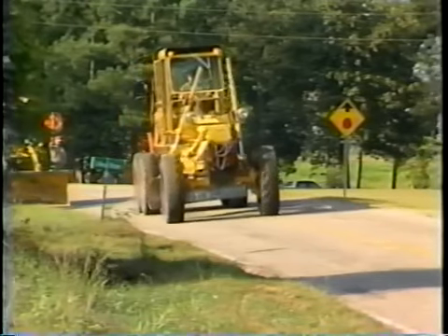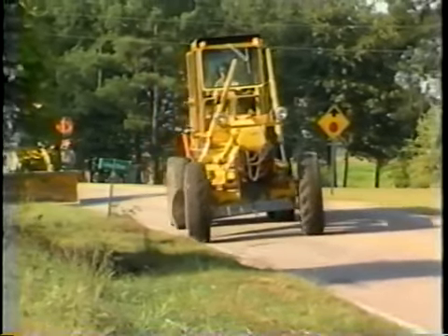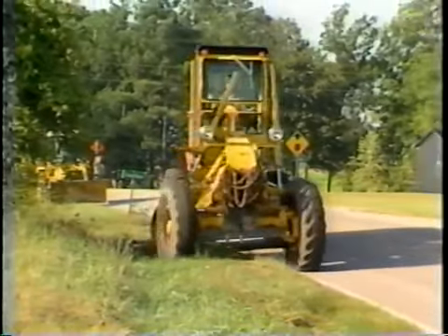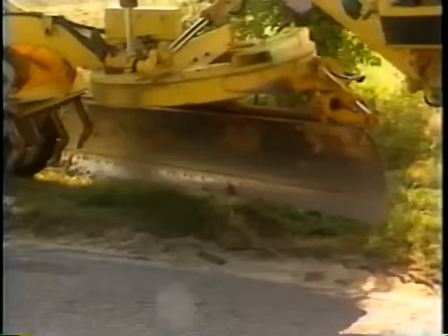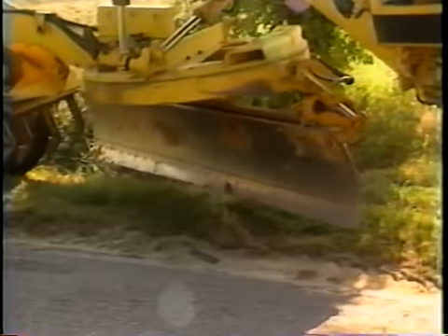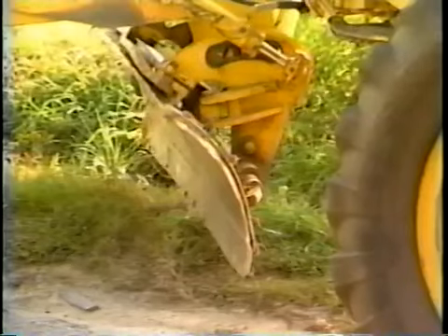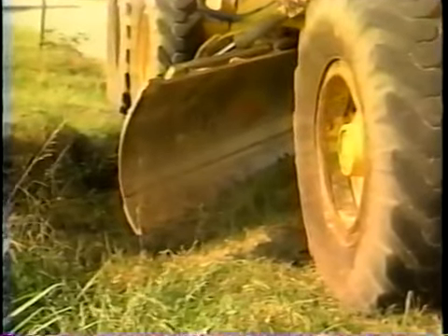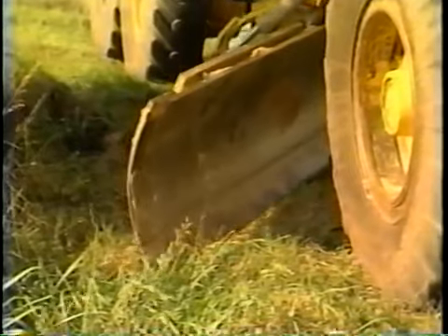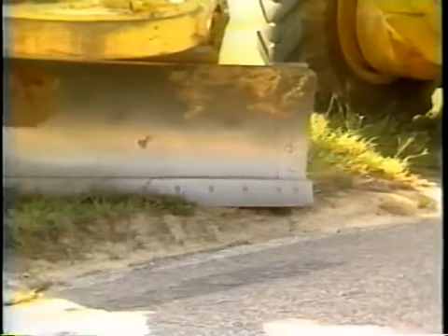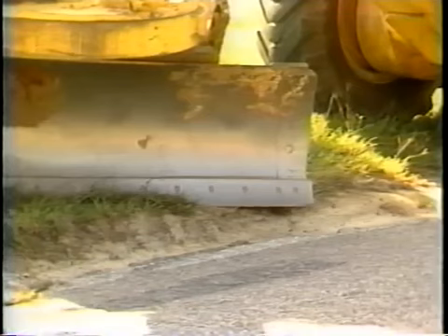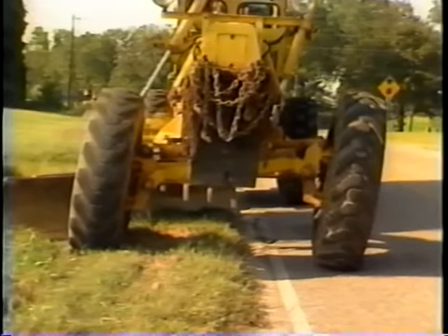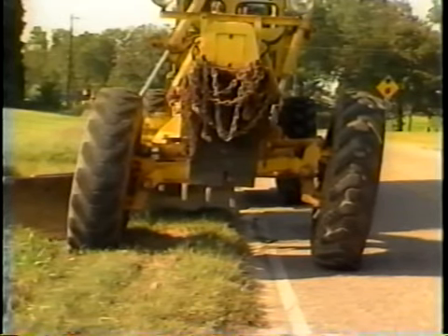If the shoulder is very hard and densely compacted, loosen the material with a scarifier attached to the motor grader. Position the grader on the shoulder. Angle the blade at approximately 45 degrees. The blade pitch is upright or tilted back slightly. Place the toe of the blade at the edge of the shoulder. The heel of the blade is flush with the edge of the pavement surface. Use a front wheel lean of 10 to 15 degrees in the direction that the material is to be moved.